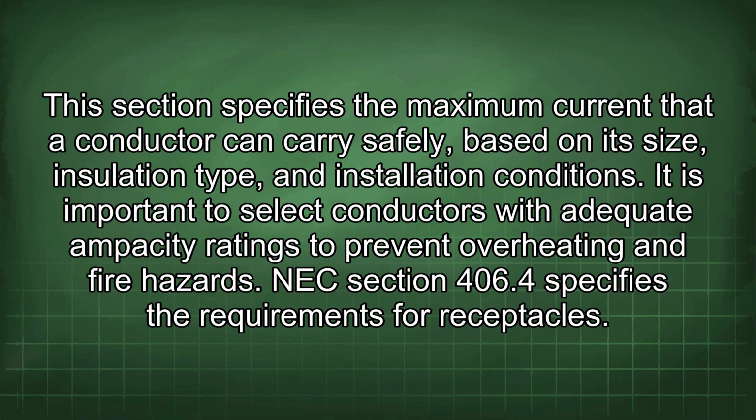This section specifies the maximum current that a conductor can carry safely based on its size, insulation type, and installation conditions. It is important to select conductors with adequate ampacity ratings to prevent overheating and fire hazards.